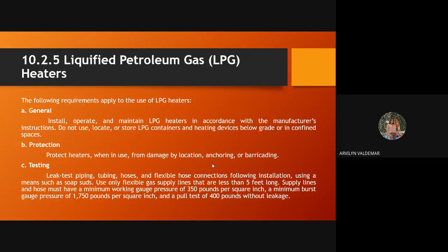Next is for liquefied petroleum gas, or LPG, heaters. In general, install, operate, and maintain LPG heaters in accordance with the manufacturer's instructions. Do not use, locate, or store LPG containers and heating devices below grade or in confined spaces. Next is protection. Protect heaters when in use from damage by location or anchoring and barricading. Next is testing. Leak test piping, tubing, hoses, and flexible hose connections following installation using a means such as soap suds.